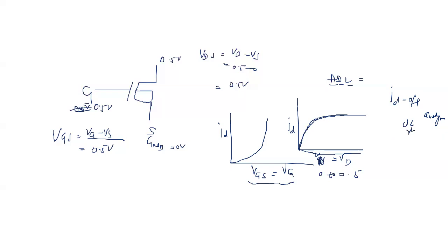And if in the DC analysis, I take VGS over here, I have taken this as X and this as Y. Now, when I select my Y from 0 to 0.5, I see this sort of a plot. Remember, whenever I go for the input characteristics, it means the gate source voltage is on the x-axis, and when the drain source voltage is on the x-axis, it means we are going to see the output characteristics.